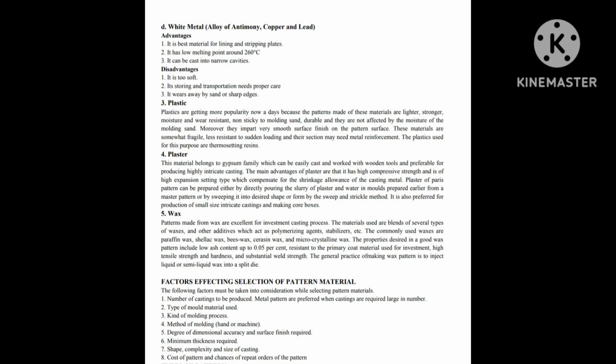3. Plastic. Plastics are getting more popularity nowadays because the patterns made of these materials are lighter, stronger, moisture and wear resistant, non-sticky to molding sand, durable, and they are not affected by the moisture of the molding sand. Moreover, they impart a very smooth surface finish on the pattern surface. These materials are somewhat fragile, less resistant to sudden loading, and their sections may need metal reinforcement. The plastics used for this purpose are thermosetting resins.